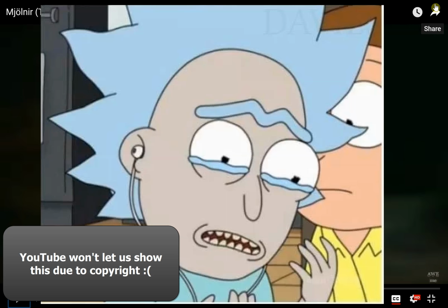It's not the same as welding, because welding means that you melt one of the work pieces. This is a third piece. So you've got your piece A, piece B. You're not melting either of those. You're melting some other material that goes between them, and that's what gets solidified. Whereas welding melts one of your two work pieces, right?